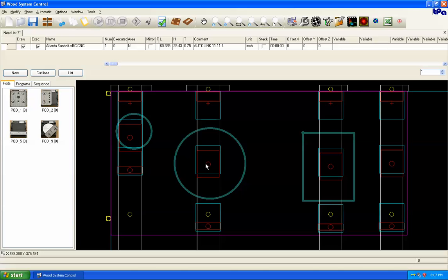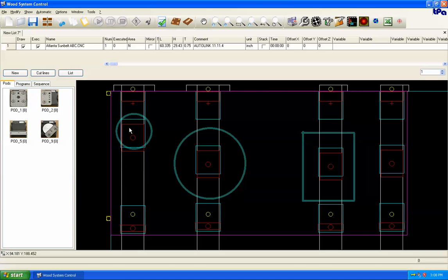So I'm putting each of the cups near the edge of the part, and also underneath these cutouts so that the cutout doesn't just fall through. We support it with a vacuum cup. Now in this case, we're not able to get a pod underneath this small cutout. So what we can do is erase this pod from the rail. And then if we want to move this one up underneath it, we still can't move it far enough because the two bases collide.